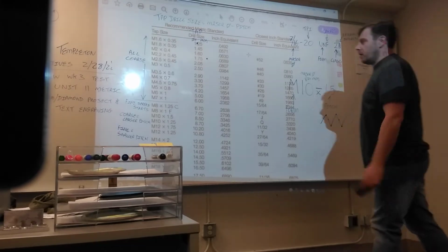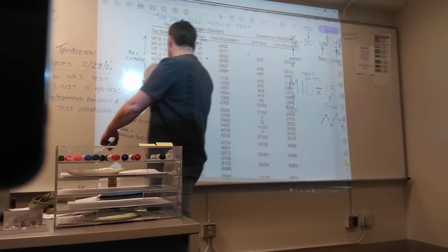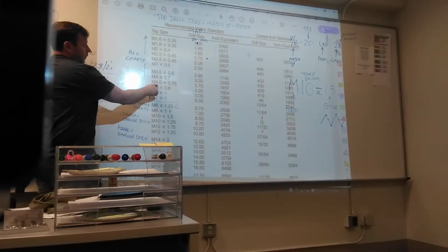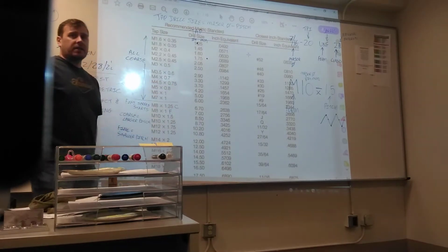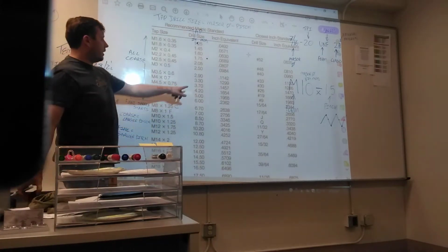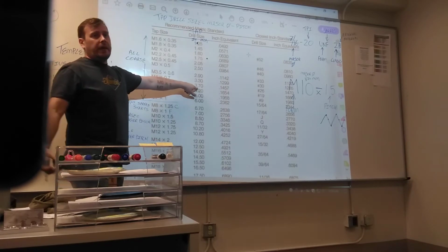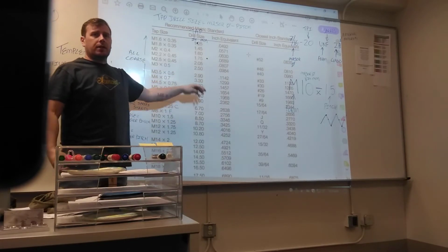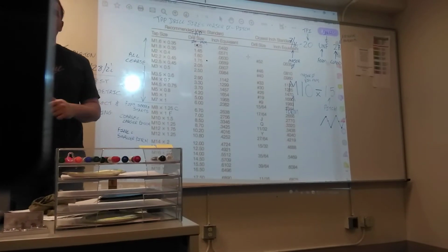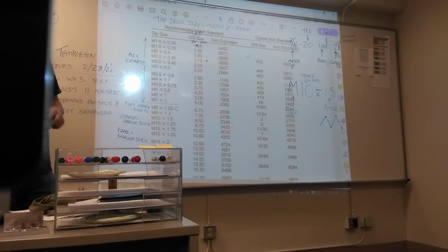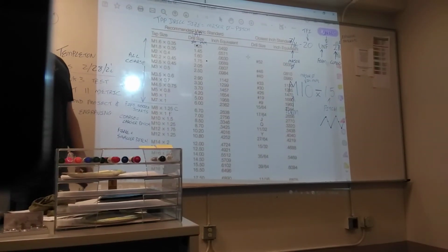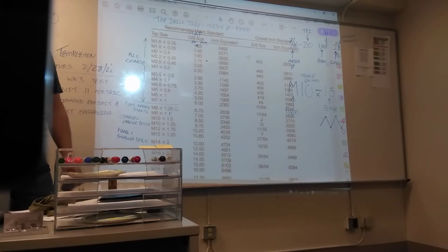On some of them, where you've got like that 7.5, if you do 4.5 minus 0.75, you don't get 3.7, you get 3.75. The reason is the increments of the drills go up in 0.1 increments. So you can get pretty much any size drill: 5.1, 5.2, 5.3, 5.4.